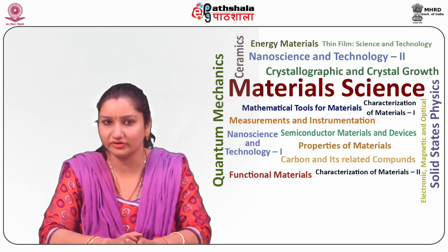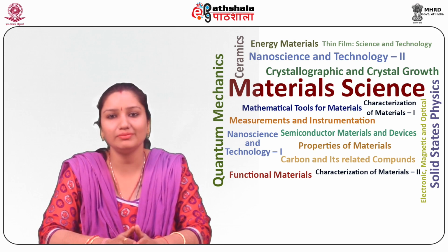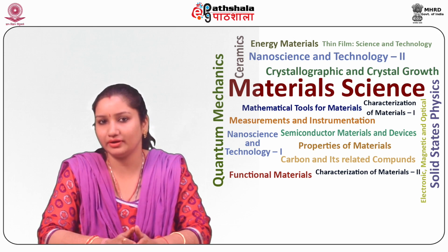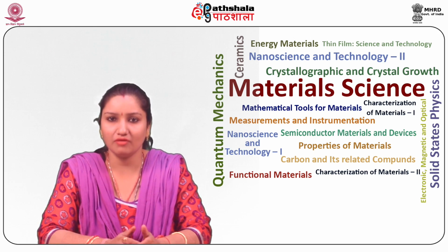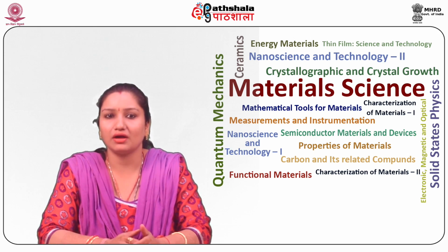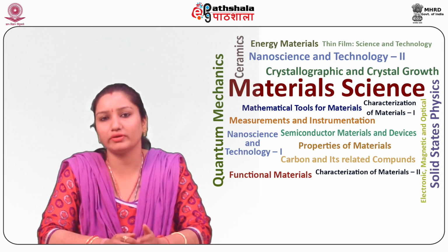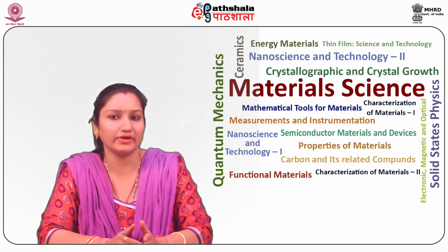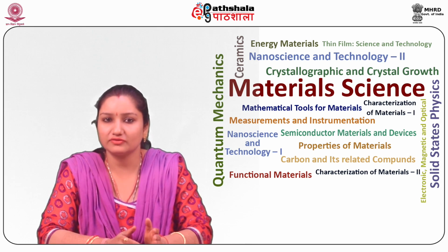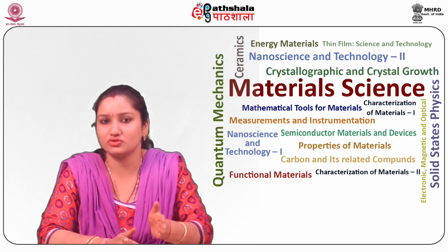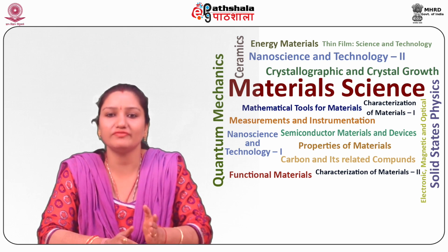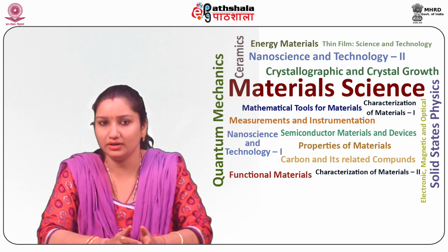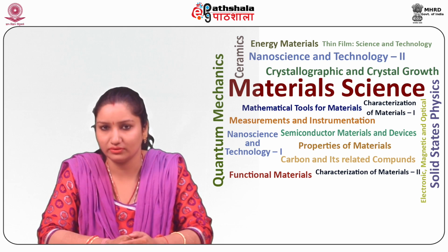Multiple beam interferometry for the measurement of film thickness can be implemented by the method of Donaldson and Tolansky, which is shown in figure 2. The arrangement differs from figure 1 in that the substrate GHJI supports a film KLMI whose thickness is to be measured.